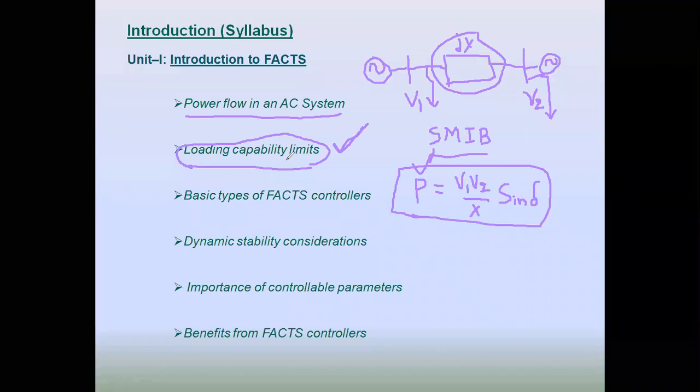Also, you have to see voltage stability, and also subsynchronous resonance. That is a separate problem you can get in the case of series compensators, which also has to be addressed. That is about loading capacity and other issues.